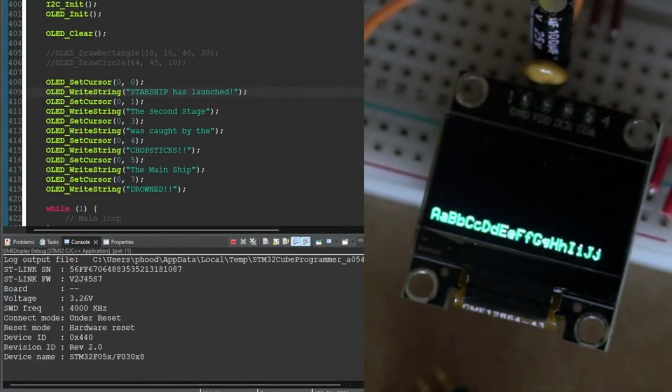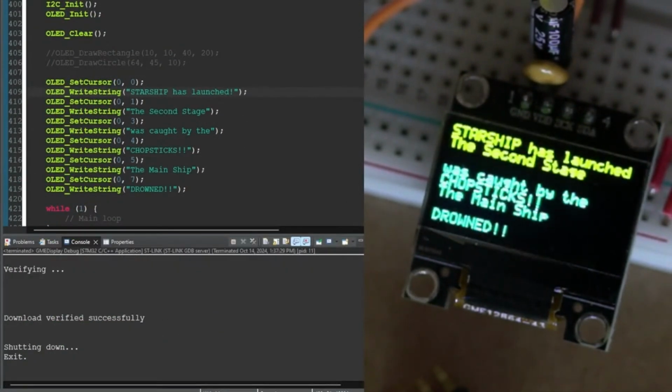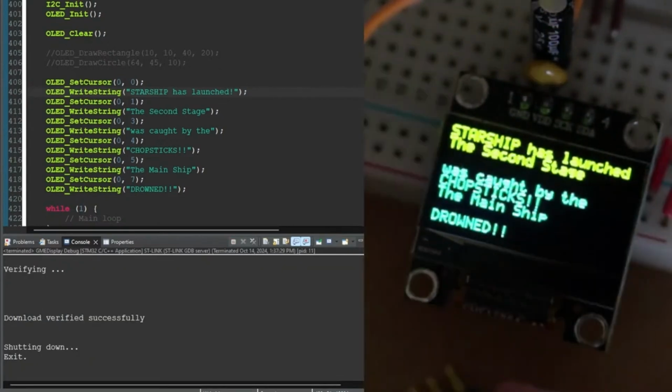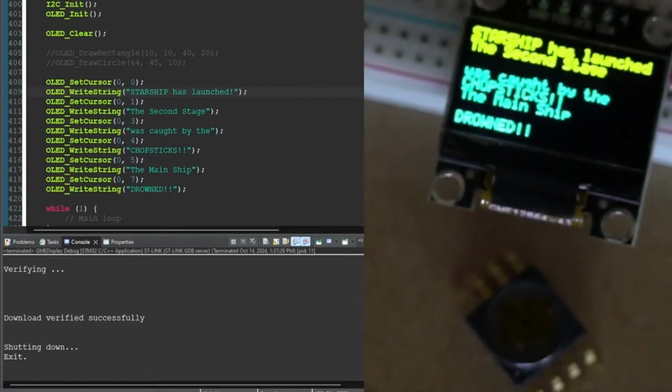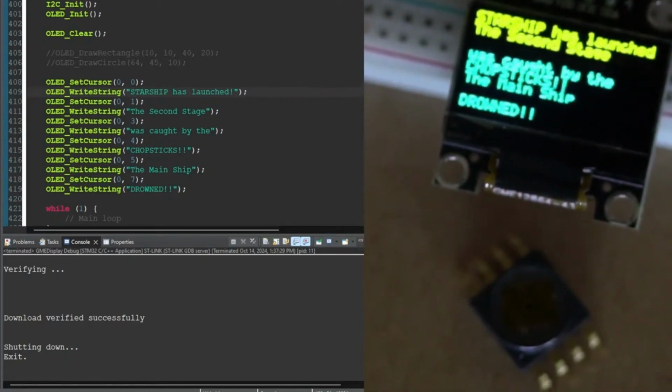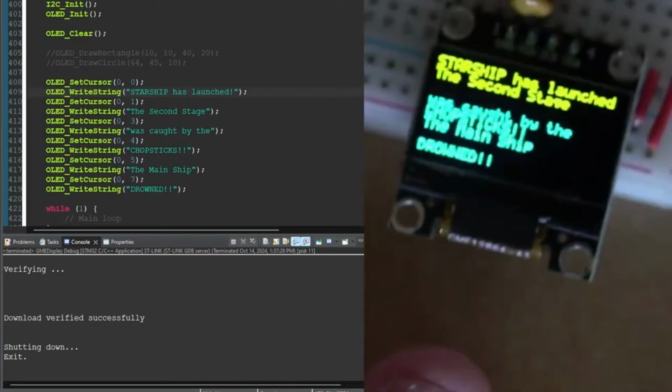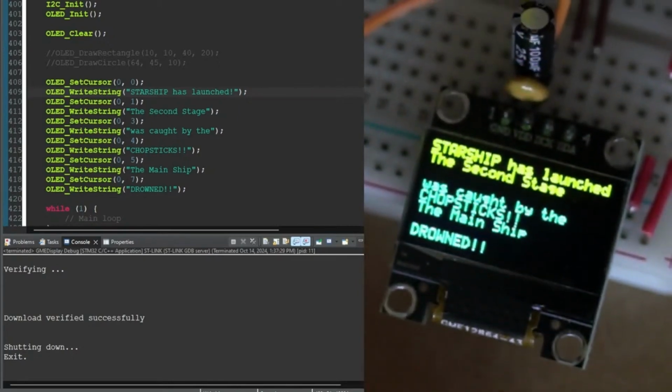From Ghana, nice. Oh, barometric pressure. No, it is vacuum. Yeah, that's good guesses, everybody. So this actually is a vacuum pressure sensor that goes up to negative 115 kilopascals, which is probably roughly 32 inches of mercury. I use it for my vacuum pressure sensor controller.